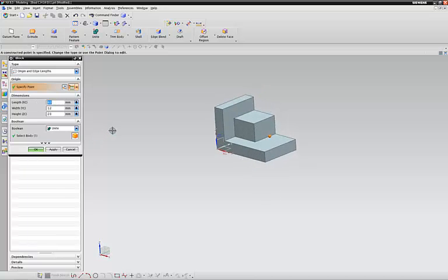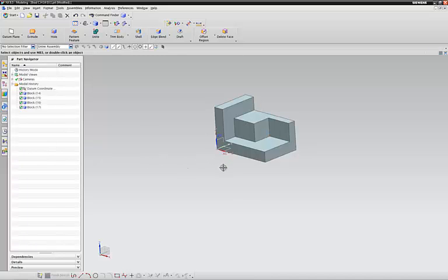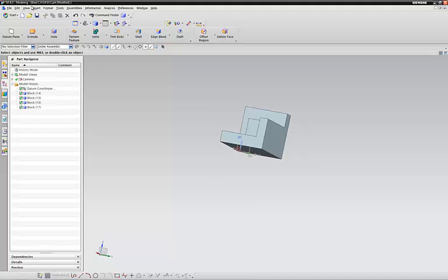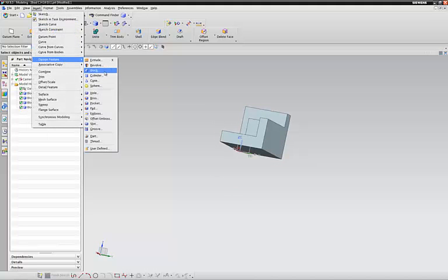The X direction would be the total length of the part, 96 minus 56. I know my X from here, so I'm orienting myself with the X, Y, and Z because I often forget which direction is which. Our Z, which is height, which is another 28. Unite. Bam. All right, one more block, and we'll be done using that command.